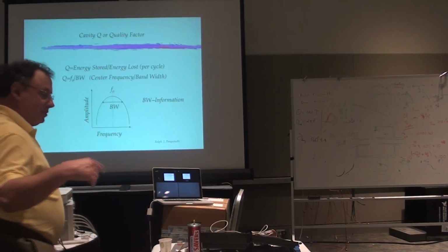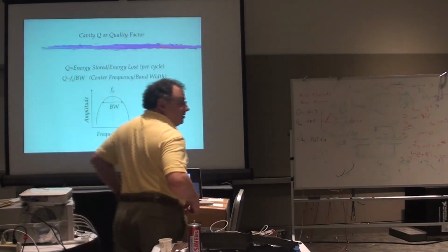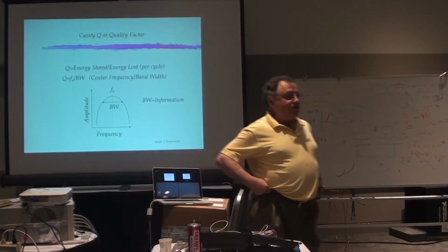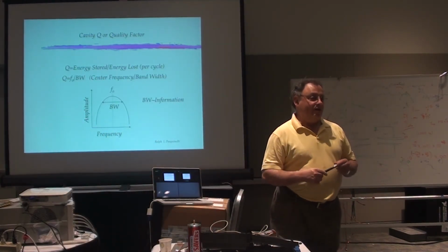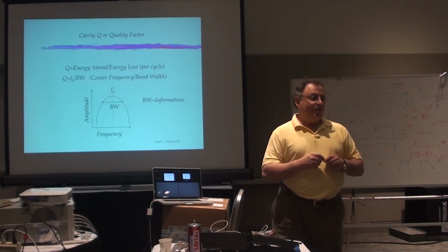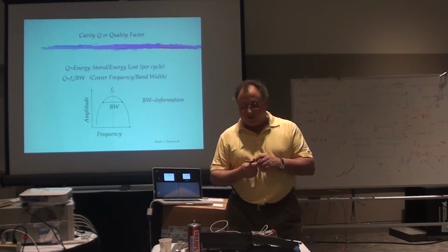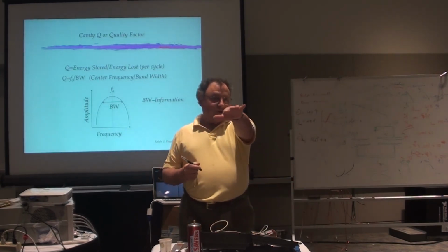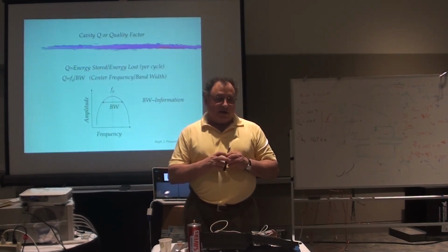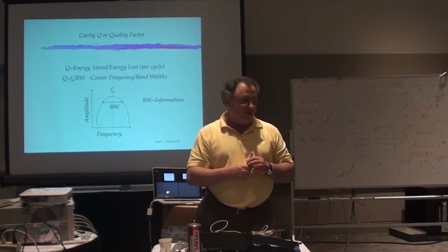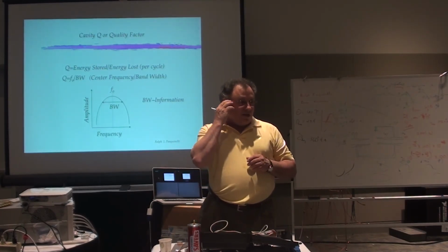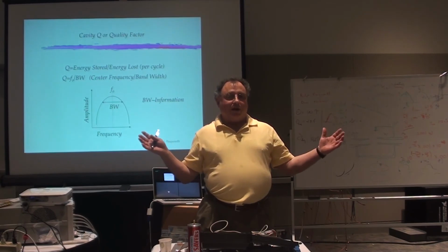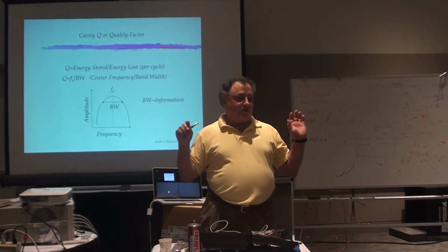The problem with that is the more elements I put in my matching network, the more loss there is. And if you're dealing at high powers, that loss is costing you money. So it's always going to be a trade-off for what you need in terms of bandwidth. If you're a single frequency, and that's what we'll be doing certainly with these cavities here, and also with the mystery boxes, you're just matching at one frequency, but when you're done, you'll open the network analyzer up and see how good it is as a function of frequency.